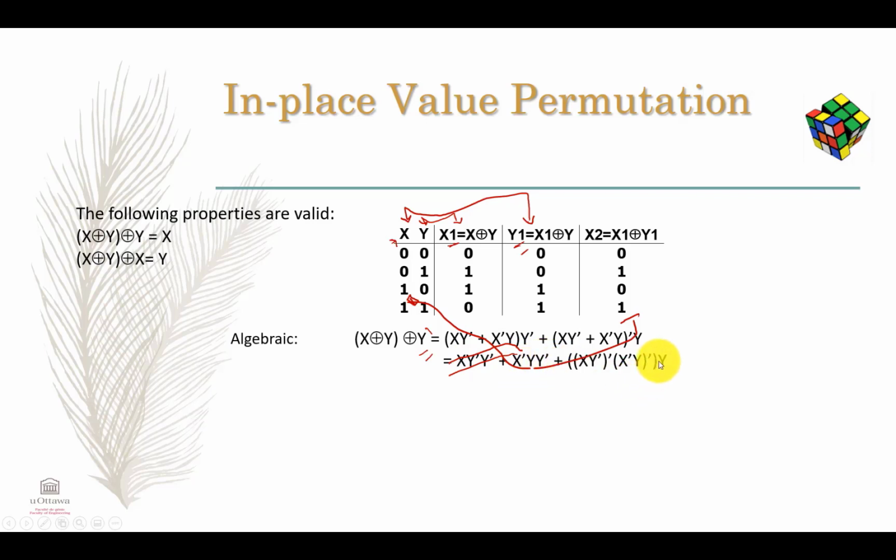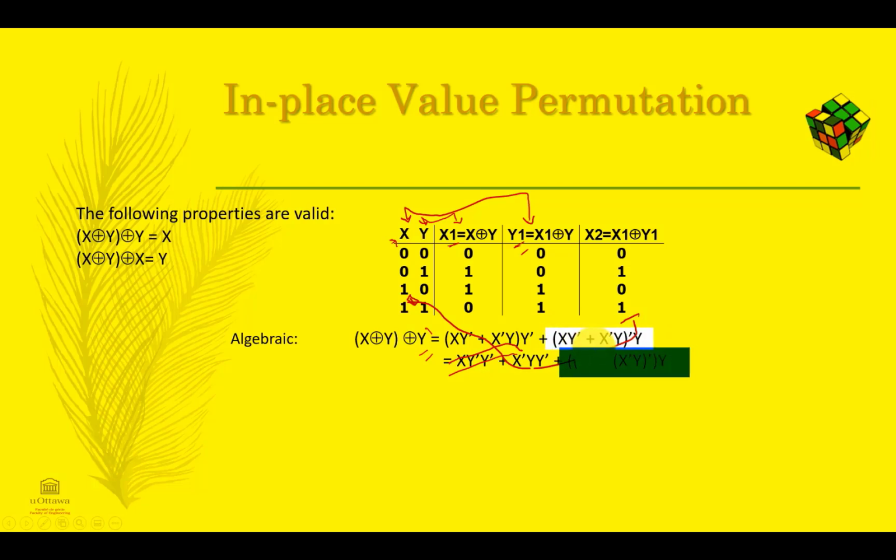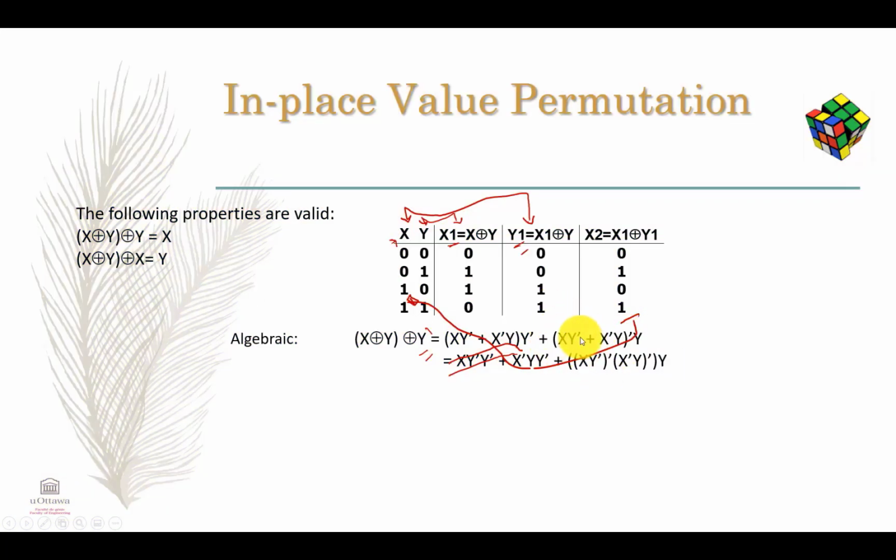And here, guys, what I did is I used DeMorgan in order to change the operation from OR to AND, okay? And then I get the complement inside. Therefore, the whole term of x prime y will be complemented, and I will multiply it with y. Then I have to see that this will give me 0 for sure, and this, like y prime multiplied with y prime, is still equal to what? To y prime, so xy prime.